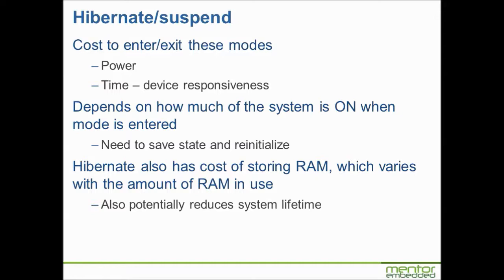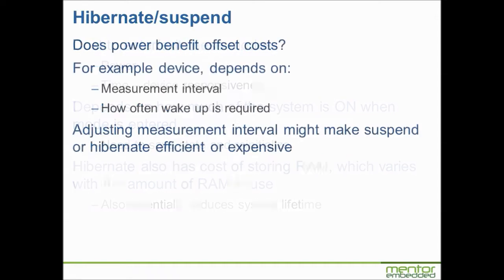I think you just heat them up to 150 degrees for half an hour or something like that, and they come back to life again, or something silly like that. Not very convenient in an embedded system, but it does show that maybe long-term this is not a worry. But for the moment, we better keep this in mind. This last factor means maybe we want to limit how often we use hibernate mode, because too often will be a problem. So overall, we need to look at whether the power benefit offsets these costs.